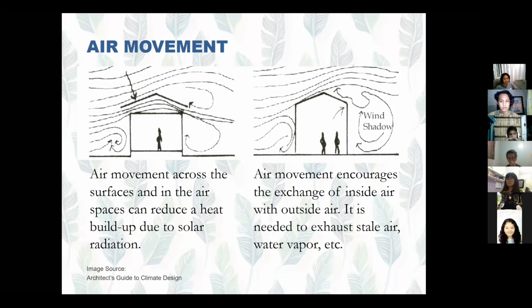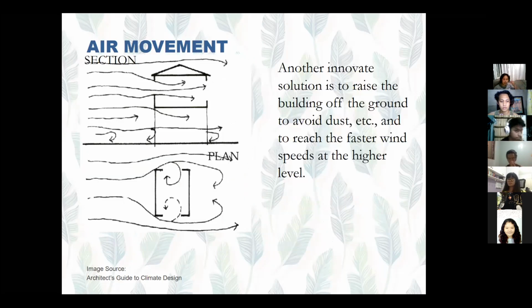Another. The wind speed in the lower part is really weak because there are many obstructions. What to do? Elevate. That is why you will notice that the houses of our ancestors are slightly elevated, right? In terms of ventilation, I have slept once in a house like that. Imagine the floor is cool and you feel the breeze in between the slots. That is tropical design.